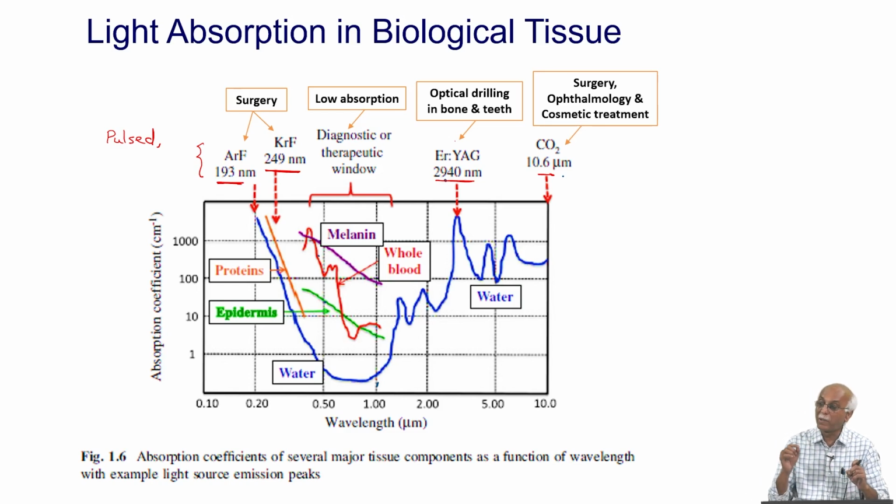When we talk about pulse oximetry, I will use 660 nanometer and 940 nanometer lines. Why shall we use those particular wavelengths? Because absorption by oxyhemoglobin, hemoglobin molecules, etc., is taken care of through that. So absorption is useful, but distinct absorption to distinguish various such constituents is also important, and that window is in the visible range.